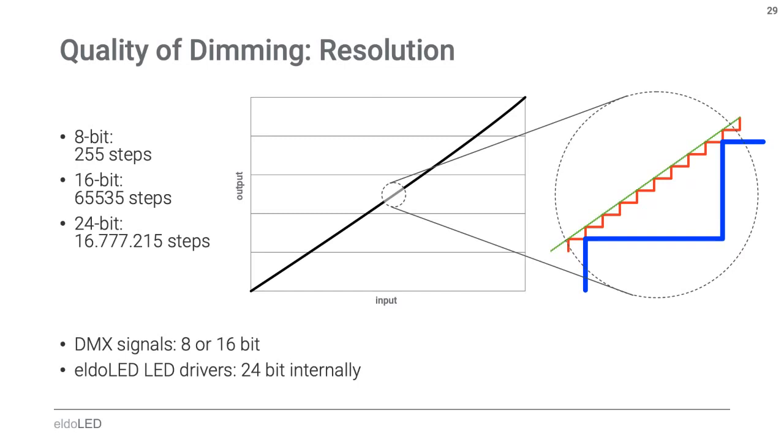And in this part, it's interesting to understand that a DMX controller towards a driver, they talk only in 8 bits, right? We mentioned the intensity for a certain channel in 8-bit, sometimes in 16-bit for certain installations, but that's where it ends for the controller. But I understand in the driver, you're actually using 24-bit.